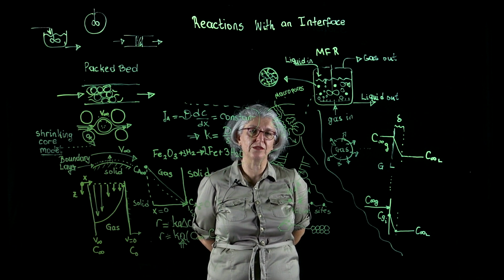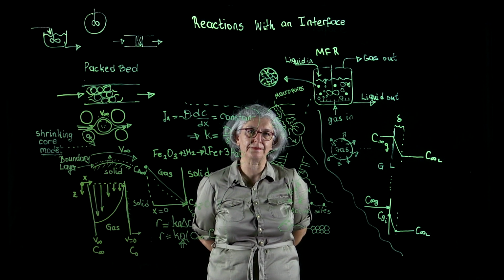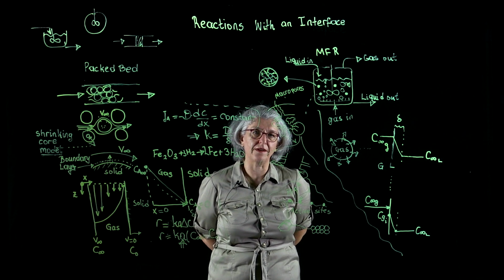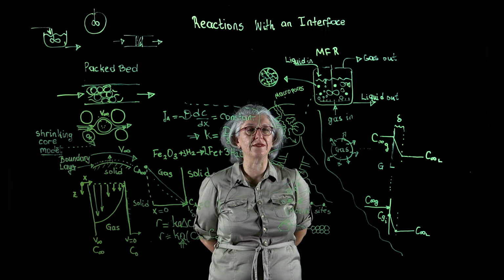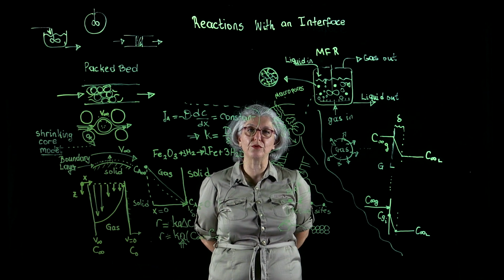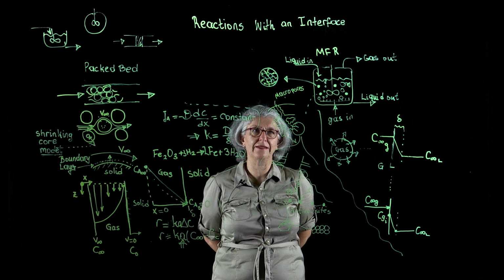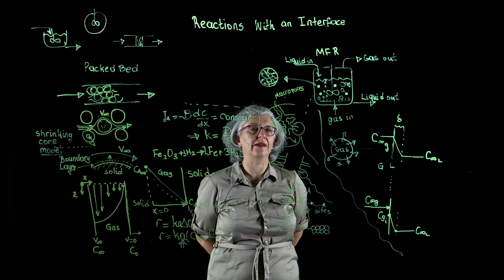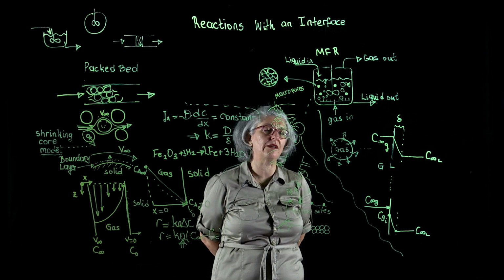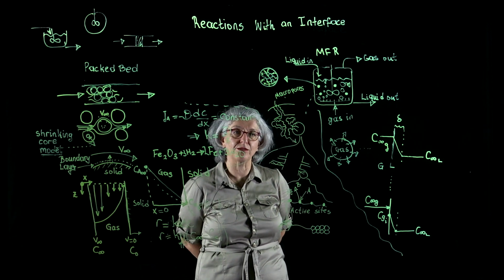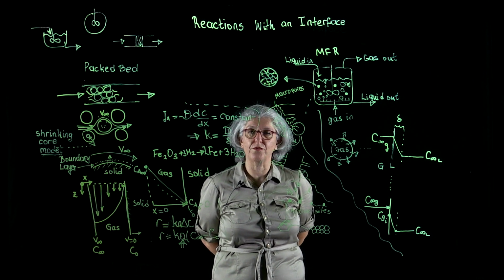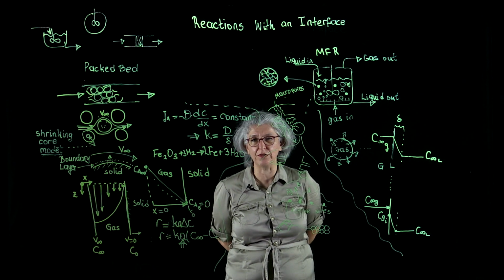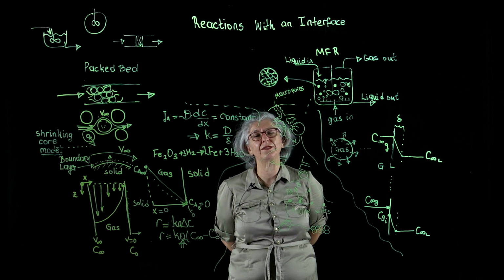And now we will learn the tools and techniques that will give us the behavior of this gas molecule on a macroscopic sense through the system. Our objective is to be able to design, to be able to estimate how much gas should I send in, how much liquid should I send in, what should be our catalyst particle size, what should be the pore size of our catalyst, and so on and so forth. All right? So far we were designing the reactors with respect to their volumes. Now we have to take a lot of other things into consideration.